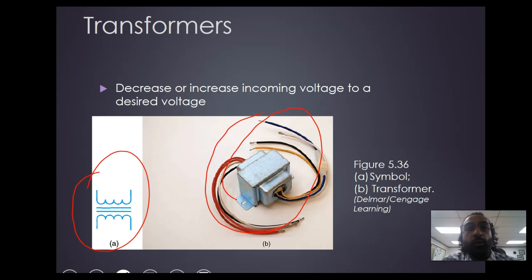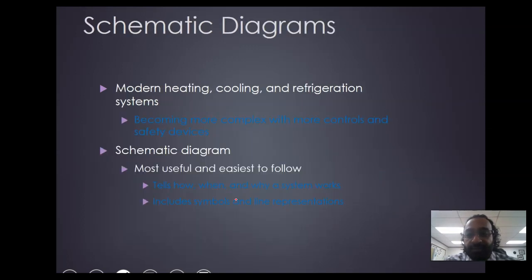And also, you don't want the thermostat to be 120 volts where you will have that control and switch in your living room. It's easier and better to have the control as low voltage, so in case there's a short, you will not injure somebody in the living space. So again, for safety, you want low voltage to be the control and high voltage outside and far away where you do the work.